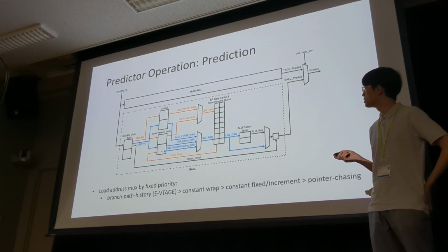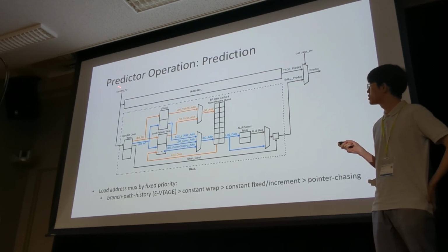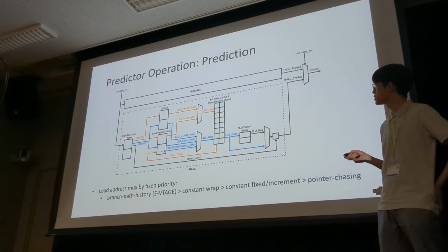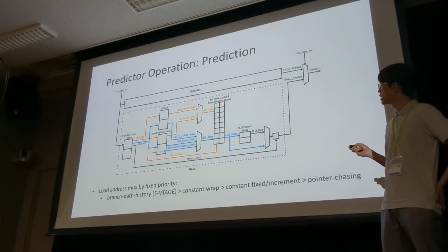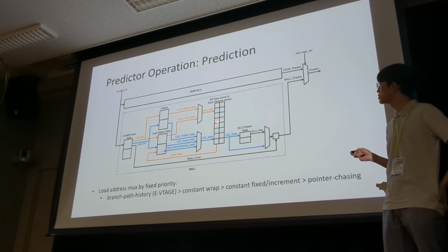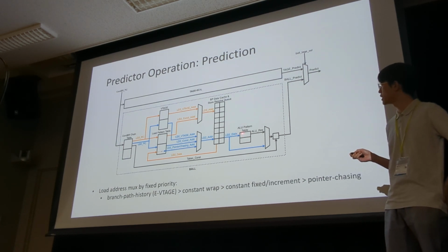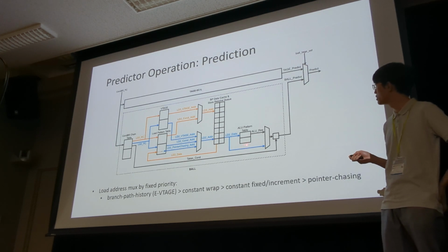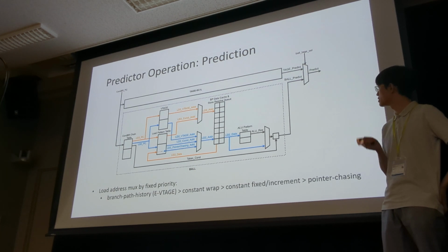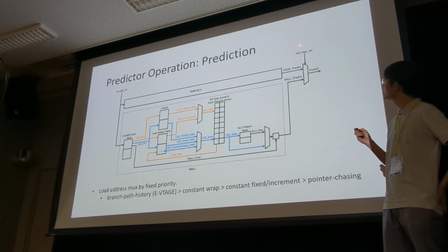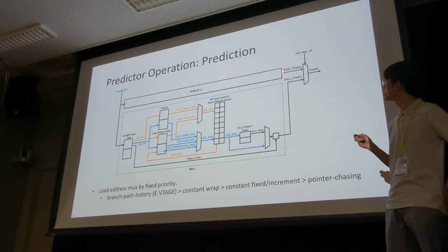So to combine all the components, when the conditional branch PC hits the conditional branch chain table, the load PC is read to look up the load pattern table and predict the load address. The load address is used to access the BB data cache and store resolve queue to predict the load data. The ALU PC will also be read to determine the ALU type, and the load data is fed into the ALU pattern table to predict the flag register value. The taken condition from the chain table will determine the branch prediction, and finally the branch TAGE selector counter will choose between TAGE and branch prediction.